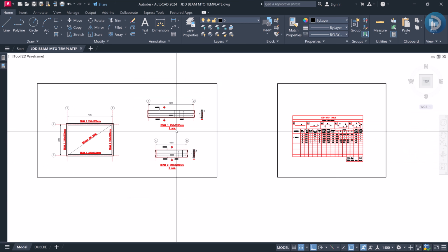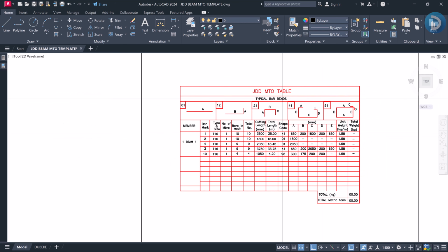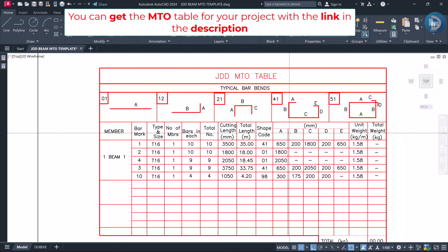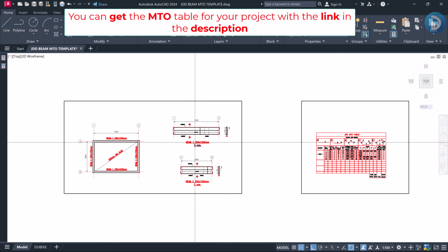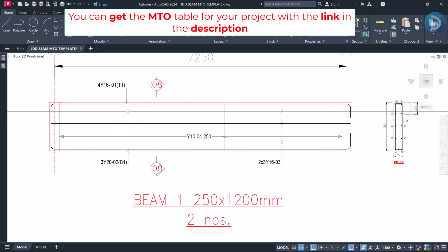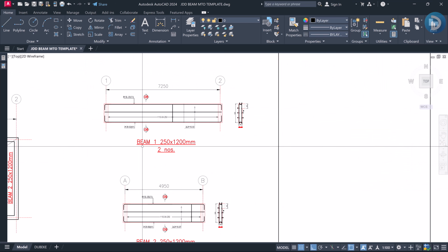So we shall be doing this in very easy steps, okay? Looking at this material takeoff table, the first step is we have to identify the various reinforcements that are in this equipment foundation beams, right? We'll get to understand the different reinforcements in these beams, and after identifying them, we get to look at their properties. In the properties, we are referring to their length, their diameters, their weights, and the total numbers in each of these respective beams.